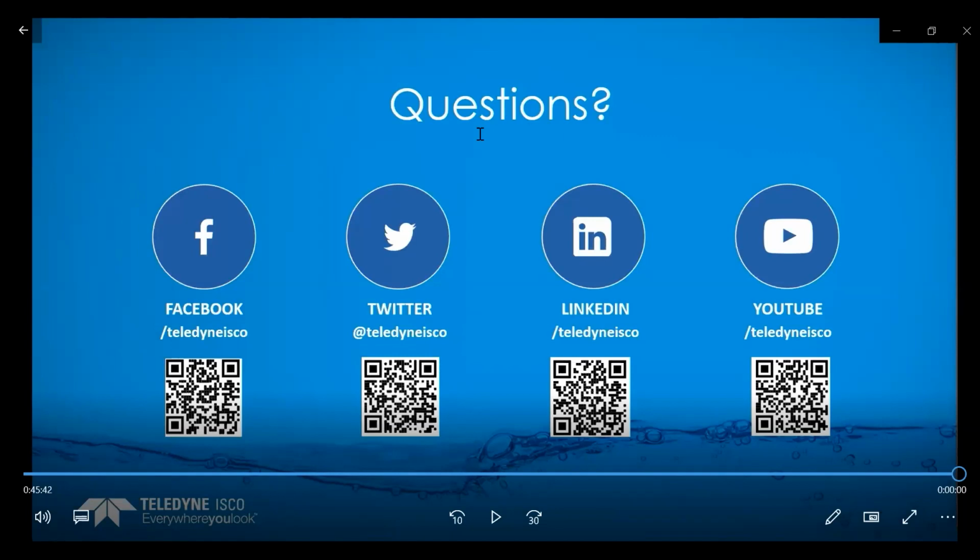But there could be some degree of error associated with the number, just simply because of how the Manning equation is deriving that flow rate and counting on a lot of variables to be stable that may not be in that particular application. So I would be a little wary of saying, yes, high degree of accuracy. Maybe we can achieve decent accuracy, again, depending upon what numbers are being applied to this low depth, high velocity scenario.